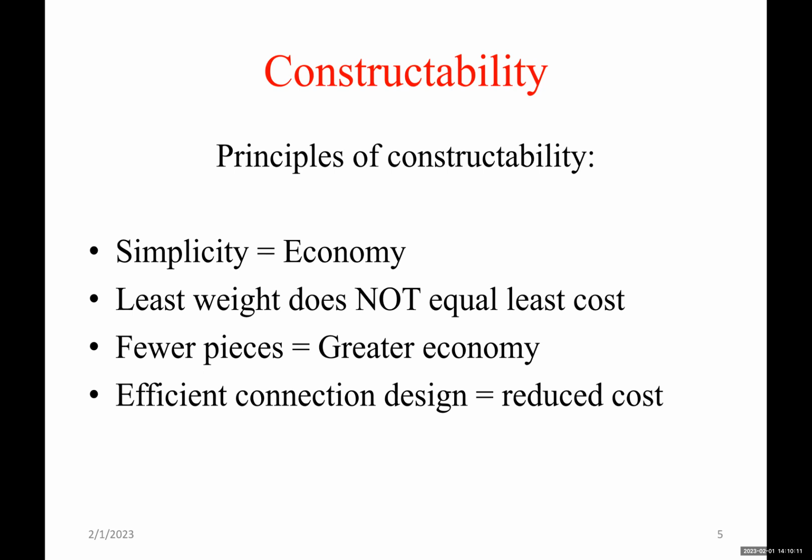If it's 200, we have to pay for 200, but this is not the only criterion for an economical structure. The price of steel is one thing, but it's not everything. We always worry about that, and we have to, but connection design is another important factor. Connections are expensive. So maybe, as you will see today, we have to increase the size of one beam,